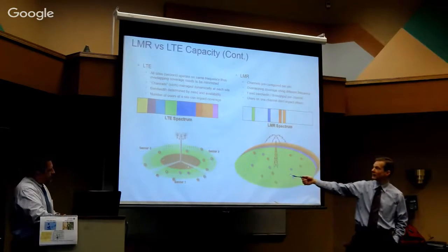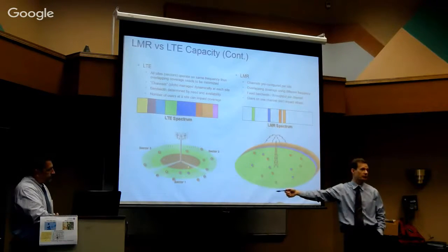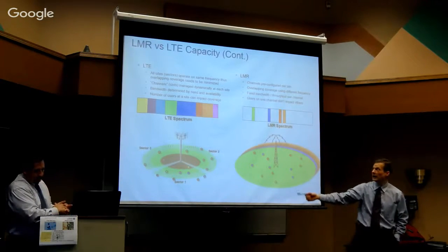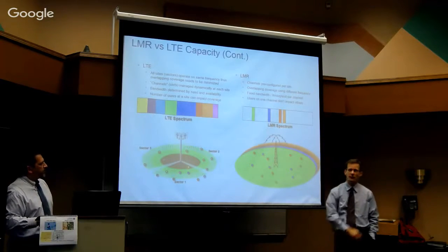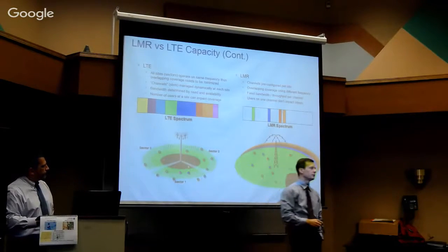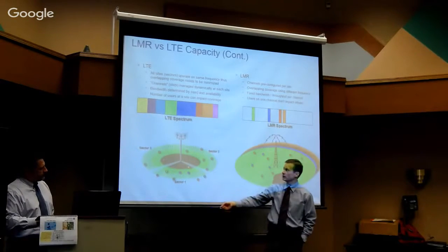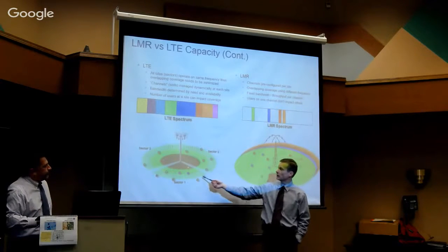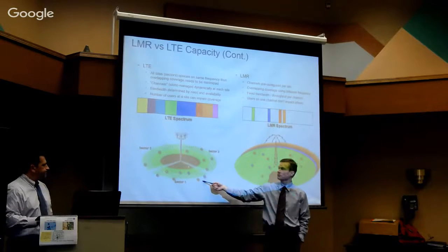But all of that has to be shared amongst a lot of different users, and they're doing different applications. Some are doing video, some are doing texting, some may be doing a multi-call, and they're all going to be sliced up differently, but they all have to use that same resource. Now, another thing, because all of these sectors are using the same frequency channel, you can't load up all these sectors 100%, right? Because if you get in between these sectors, or you've got adjacent cell sites here, they're going to start interfering with each other, right? Because they're all using the same frequency at the same time.